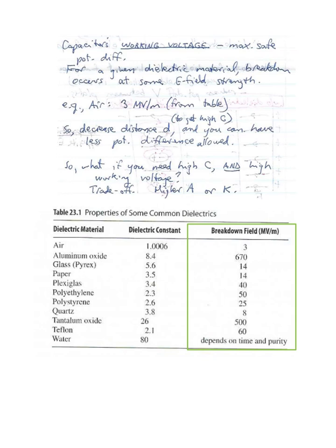So engineers who use electronics, maybe computer engineering, any kind of electronics engineering, are often limited in space because we like to make our electronic components smaller and smaller to fit into tighter spaces. And so they have to work with this trade-off: we want a high capacitance, but we're limited by the distance between the plates, the area, the size we can make them, and the dielectric constant to use. And there'll be an example coming up about these trade-offs.